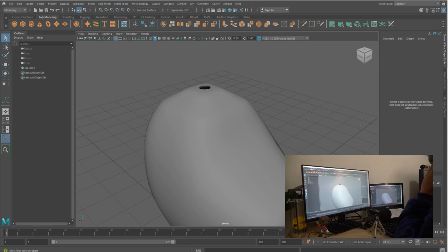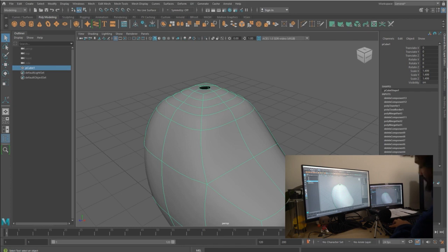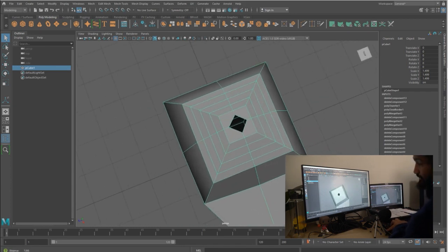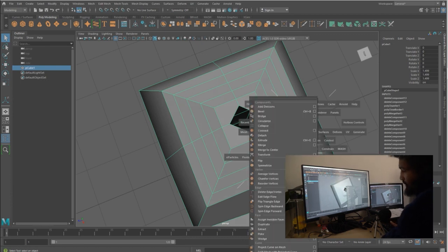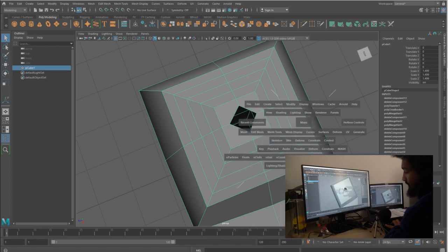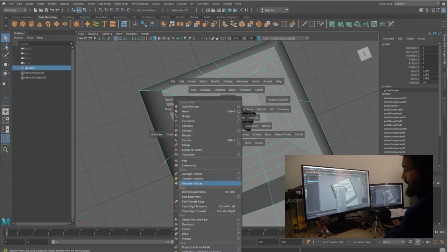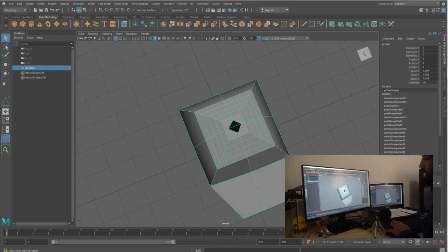Why is this a good tool? Because it's making the hole based on one vertex, so your geo is gonna keep clean. It's very important to model in a clean way. So now you're just learning the tool, but at some point you're gonna want clean meshes. So this is a kind of tool for cleaning, for making a hole and stuff like this. I'll let you experiment with the other tools here, but this is the main one you need to know. So let's review a bit.